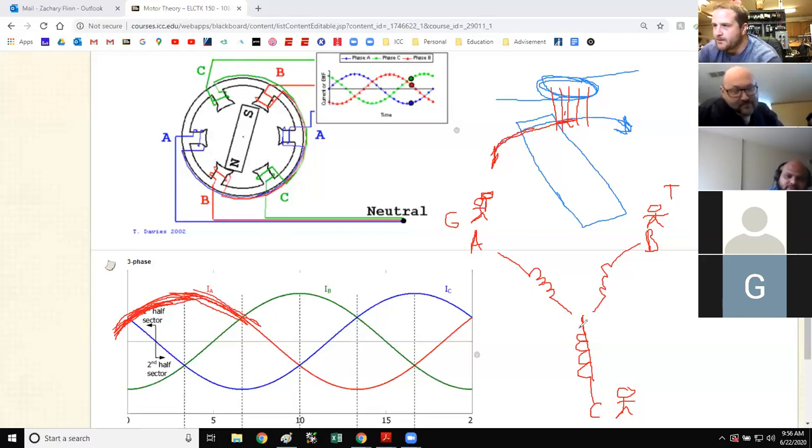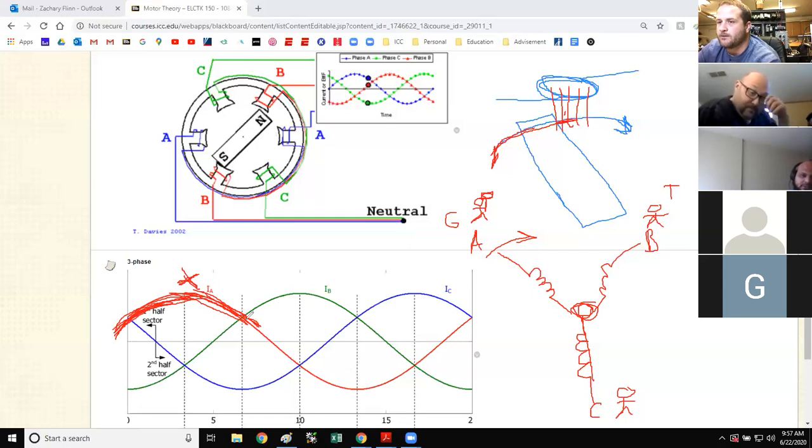So on the inside of this motor, we have a shaft that we're going to apply current to these windings. And depending on how we phase it, it's going to turn in a certain direction. And I'll come back to that in a minute. But let's say we're going clockwise, A, B, C, A, B, C, right? So every time Garrett applies current to this winding, he hits that thing with a hammer, right? And then it goes this way. Now, Garrett on the graph has just hit this thing with a hammer to keep it moving. It's going away from Garrett now.